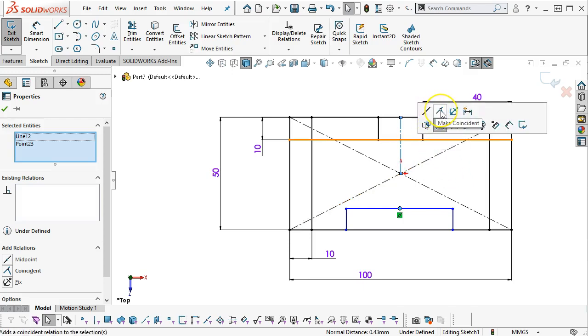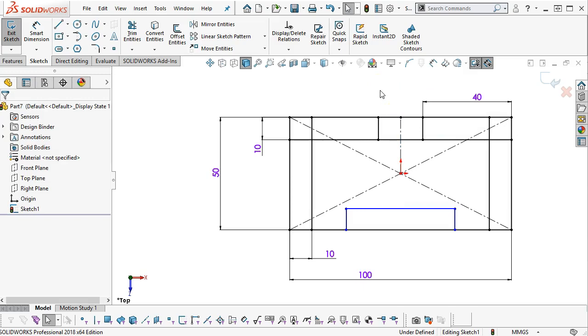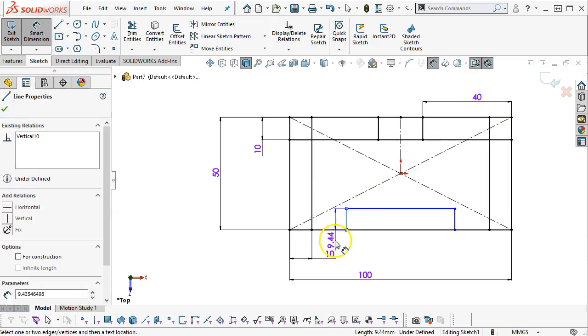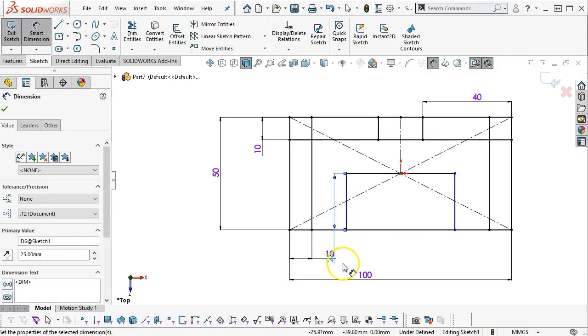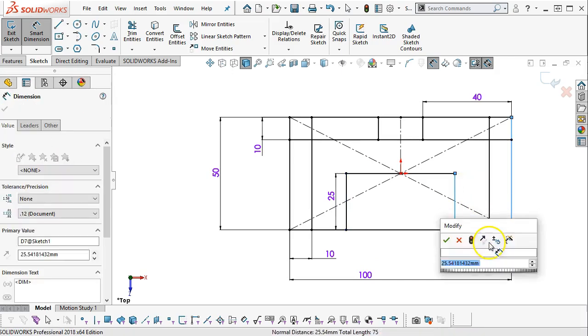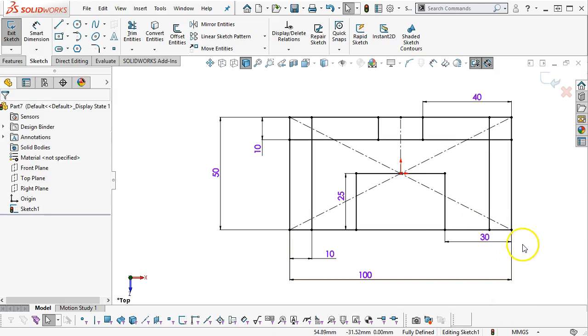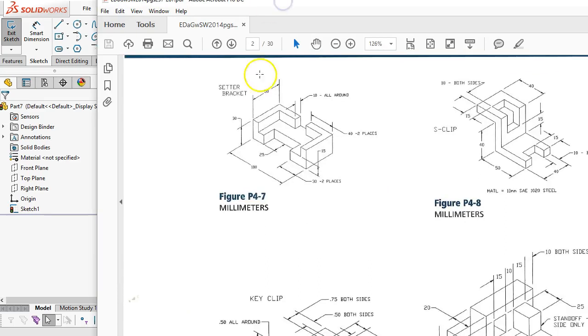All right, so this is one of those cases where I pick the line and a midpoint. I can make those coincident. That is also going to add symmetry. So depth-wise is 25 millimeters. And then as far as my dimension scheme, my metric defaulted to ISO, and I'm reasonably happy with ISO, so not anxious to change it. So this is pretty much my top-down view, all kinds of geometry, even some extra geometry, and we're going to pick up those contours and regions to build this part.